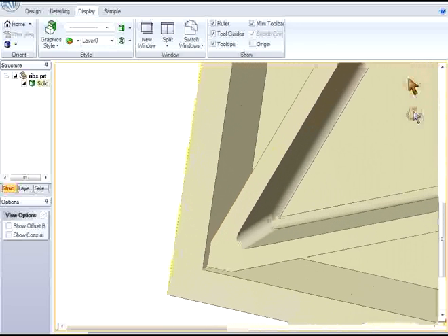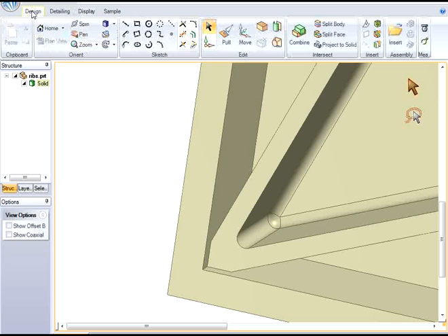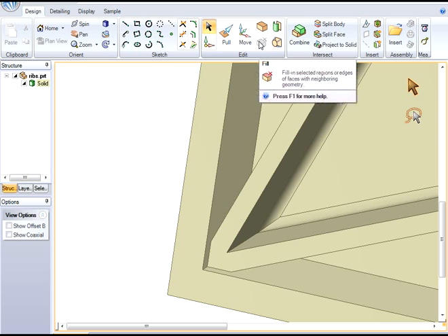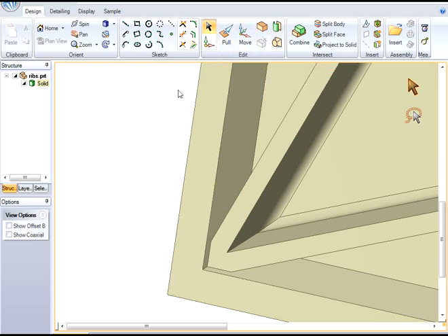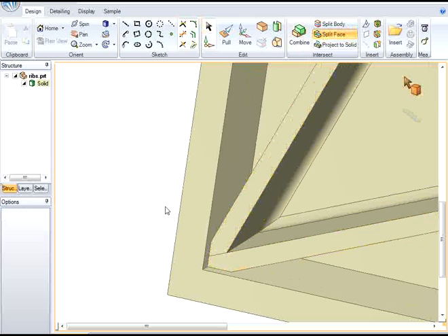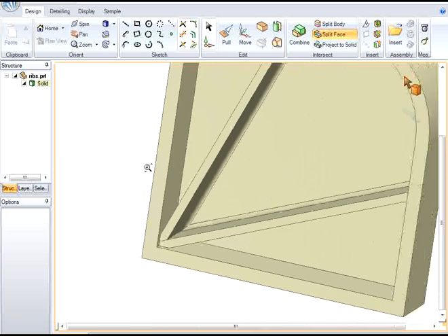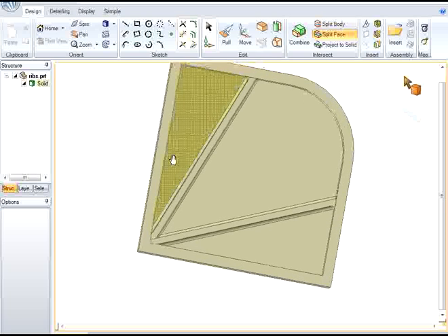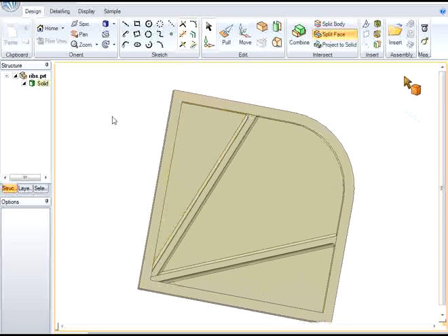One thing that's kind of neat, we can come in even on a very complex round like this cylindrical portion there and a spherical portion, and I can just say fill in that geometry. And you see the other rounds right next to it update. And now what I'm doing here is just splitting that surface on the top so that the top rib and the bottom rib are completely separate now.